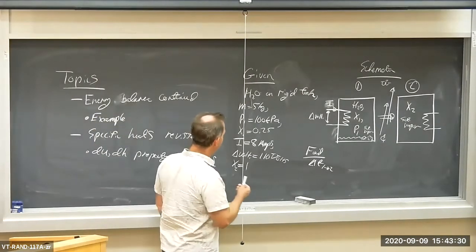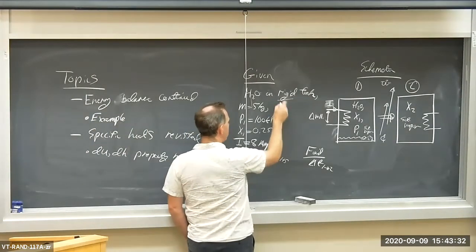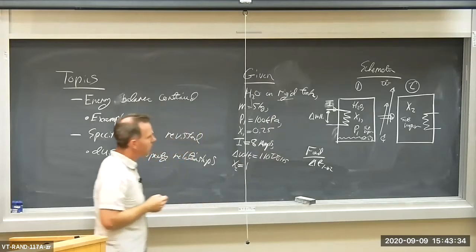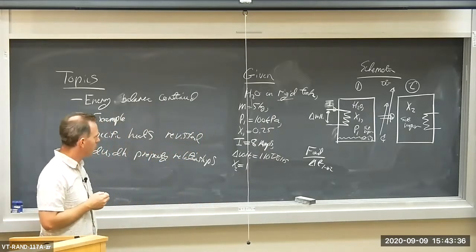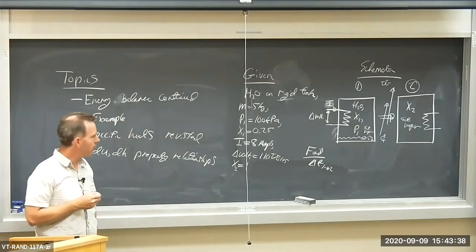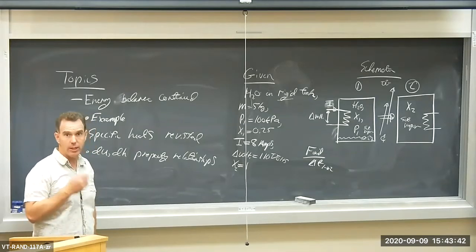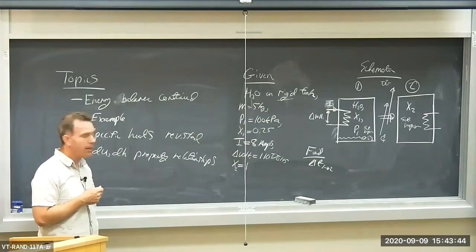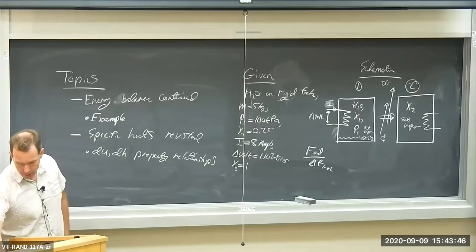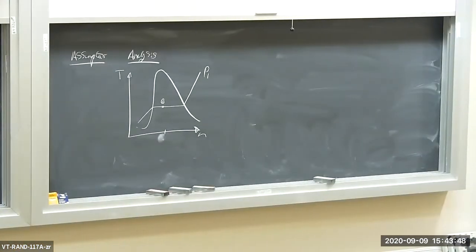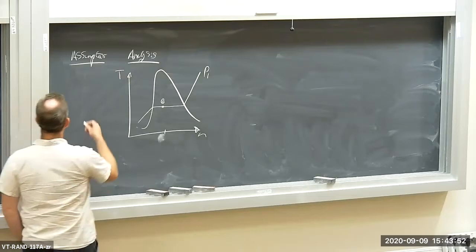So we have a rigid tank undergoing some sort of isochoric process where we're boiling away the liquid H2O. If it's rigid, what kind of process is it? It's isochoric. Rigid tank, that means isochoric. So I'm going to put up here in the assumptions, isochoric process.